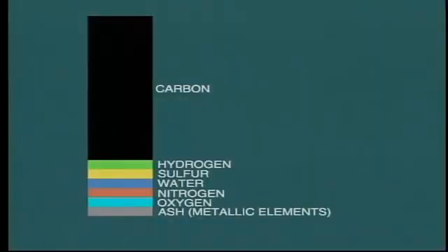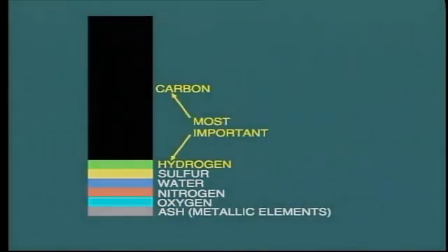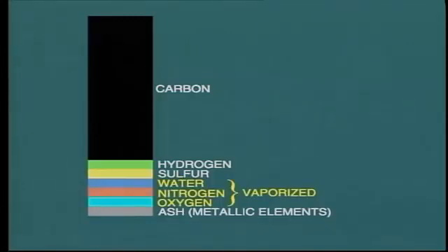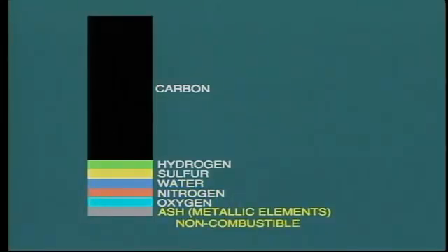What is in these fuels which causes them to burn? Well, the most important combustible elements are carbon and hydrogen. Sulfur also burns, but releases only a small quantity of heat. Other ingredients in the fuel, such as moisture, water, nitrogen, or oxygen, are vaporized. Other constituents of the fuel, notably metallic elements, are non-combustible and remain as ash after combustion has taken place.